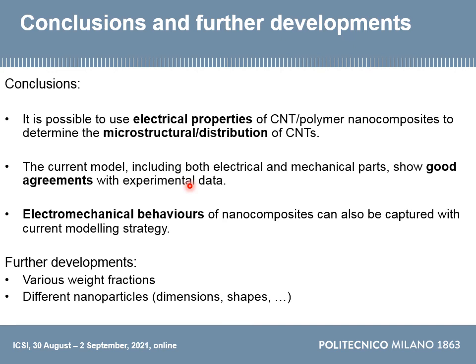About the conclusion, I'd like to say that through the current work, it is possible to use the electrical properties of the nanocomposites to determine the microstructure or the distribution of the CNTs in the nanocomposites. Also, the current methods allow us to mimic the electric and mechanical properties of the nanocomposites, and the electromechanical behaviors can also be captured.